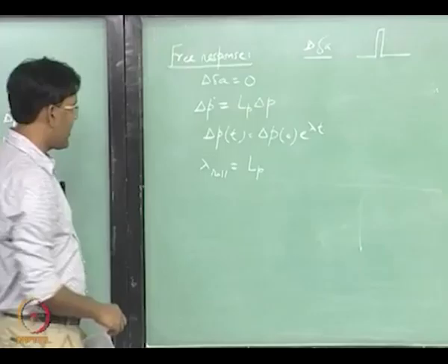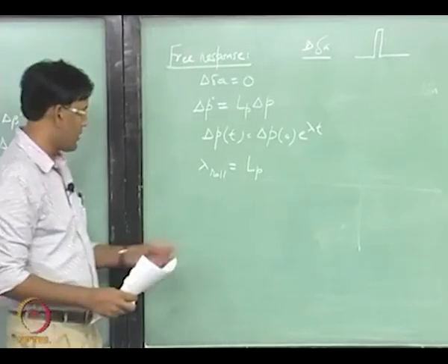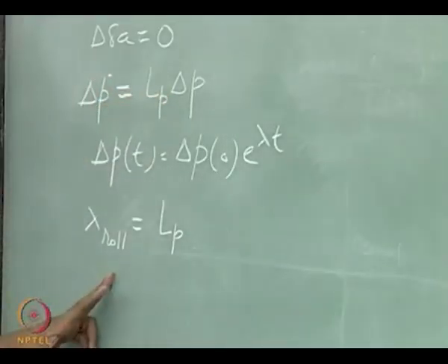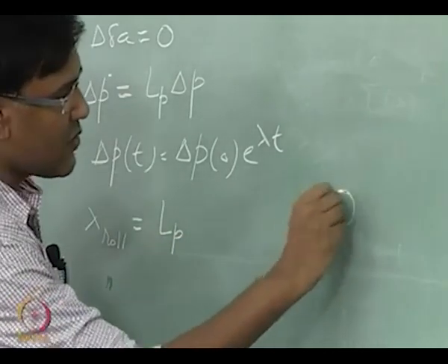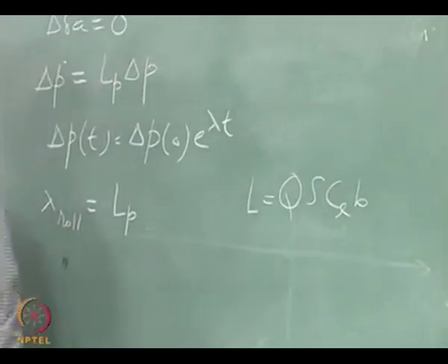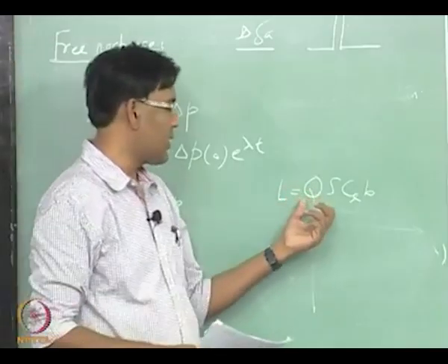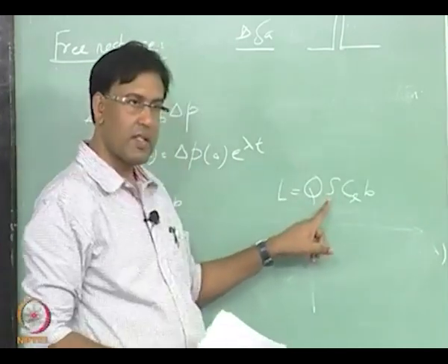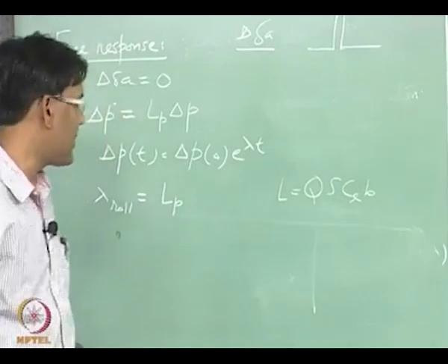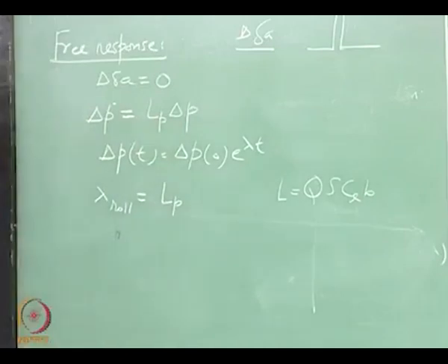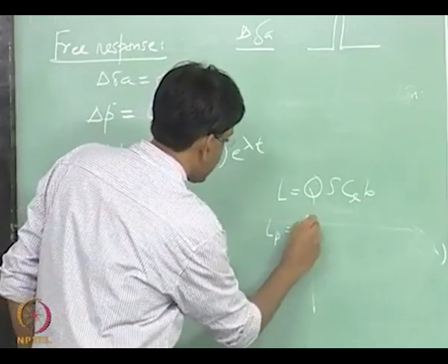Okay, so the eigenvalue corresponding to this particular motion, constrained motion, is equal to Lp. What is Lp? L is Q S Cl into B, right. So Q is the dynamic pressure, half rho u naught squared. S is the wing planform area, Cl is the roll moment coefficient, B is the span of the wing. Lp is...